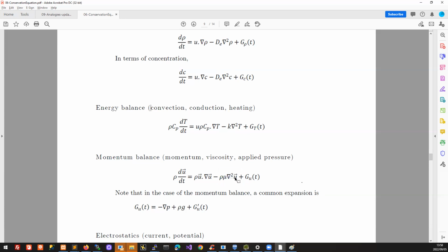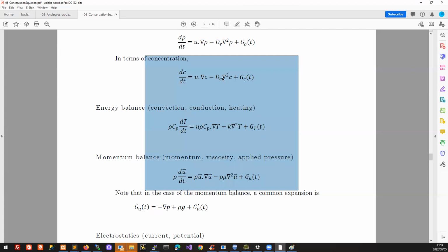And if you do the derivation, you'll find it has a second order dependence with velocity, energy second order with temperature, mass second order with the mole fraction or concentration. And so in a way, all these balances have the same form. So those are two huge generalizations that we are looking at here. One, a massive generalization in coordinate systems, in spatial dimensions, and two,